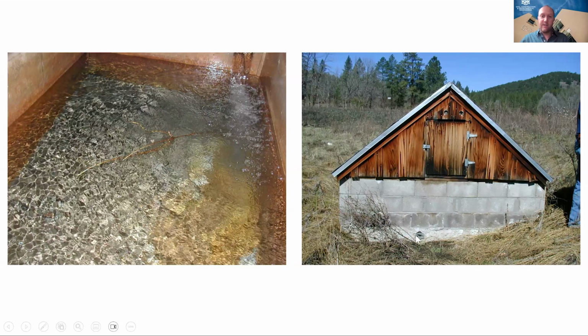So this is another situation where that spring, which originally probably was considered groundwater, is now regulated as groundwater under the direct influence of surface water, because it has a potential for contamination from surface water. So it would be regulated more strictly, in more of a similar way as surface water. Oh yeah, and the vent is actually an overflow. Thank you, Matt. Matt's the one who took that photo.